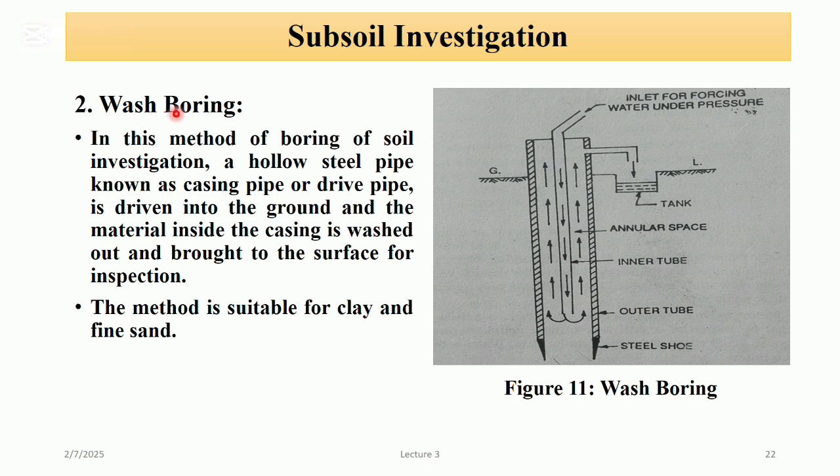Wash boring. In this method of boring of soil, a casing pipe is driven into the ground and the material inside the casing is washed out and brought to the surface for investigation. This type of boring can be conveniently used for test boring over 3 meters in depth and in soft to stiff cohesive soil and fine sand.